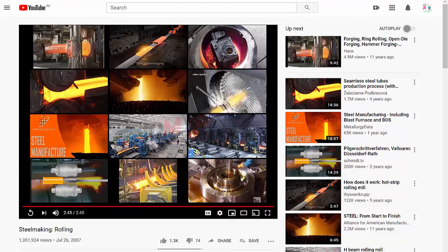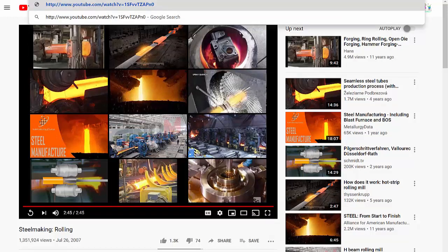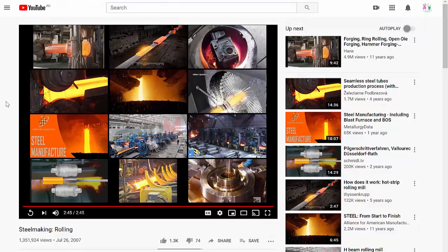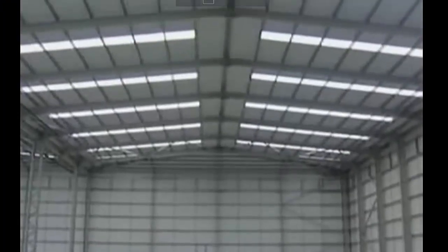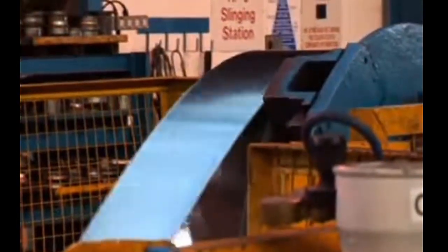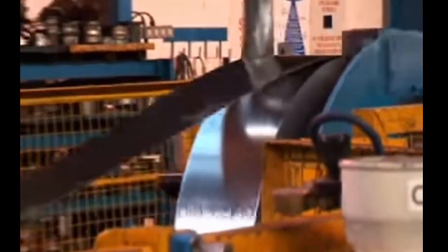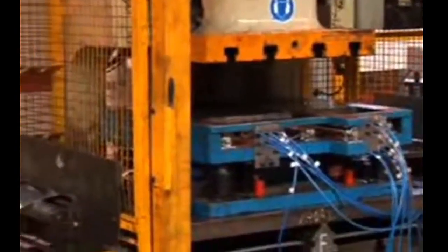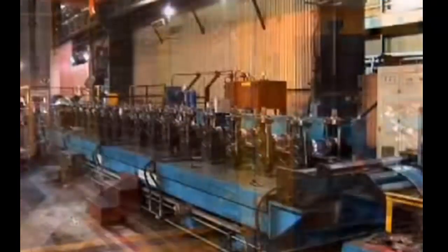And now for the cold form steel, here is another video from YouTube again showing how the cold form steel is produced. Cold formed sections are used for a number of different applications, primarily associated with either the building envelope or light steel structural elements used in walls, partitions or floors. For the building envelope, narrow strip steel is rolled into the sections required for purlins or sheeting rails that support cladding and sheeting.